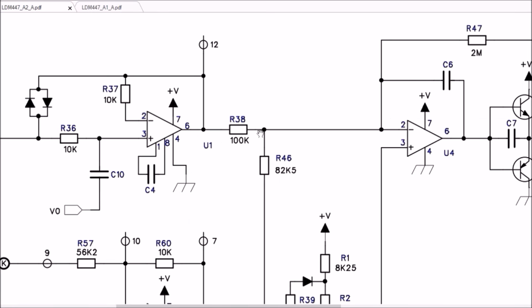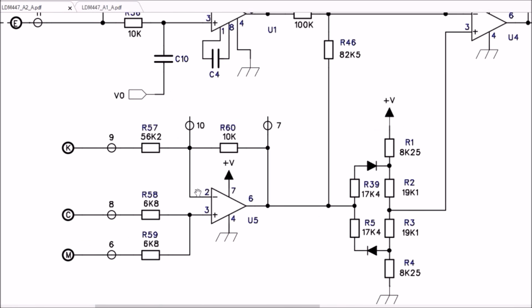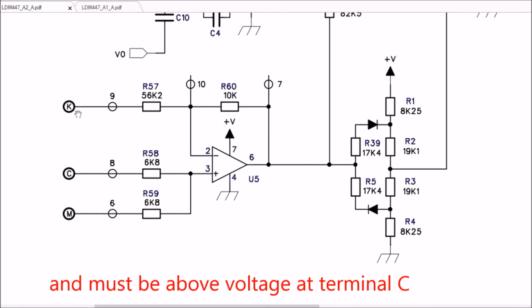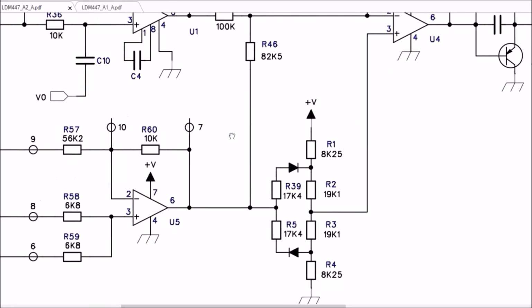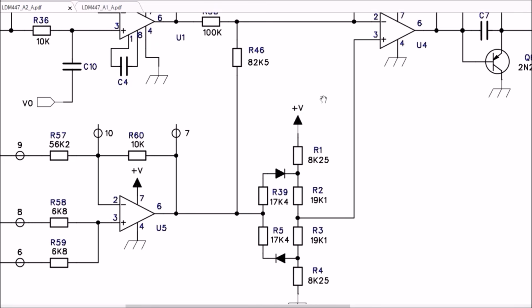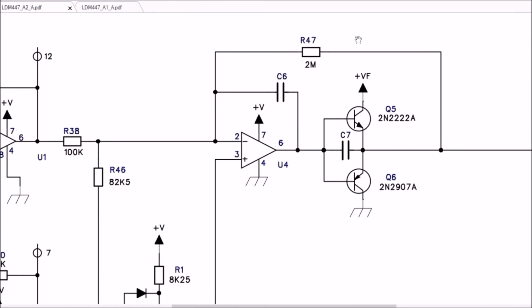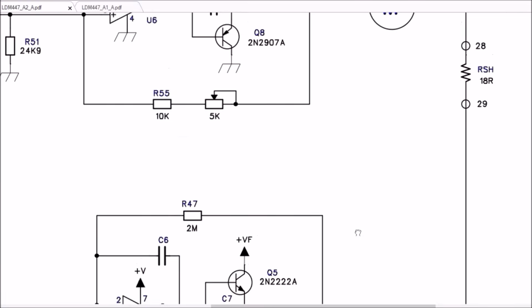And here we have the summing point. So this is the virtual ground. So you can use the input as an inverting amplifier. In that case, the input voltage is positive. We have a voltage limiter, and the difference of these two currents here flows through the feedback resistor, and the output here is fed to the DC motor.